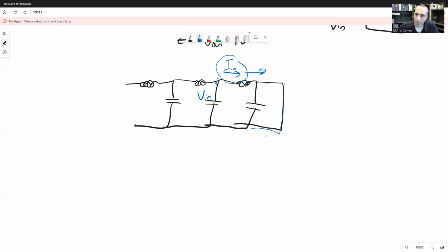All right, so we have this incoming voltage that's established. And the reflection is basically going to be another voltage, an I in, that's established right here, and is going to cancel out the voltage that had appeared momentarily on this next to last capacitor, and that cancellation will move onwards.